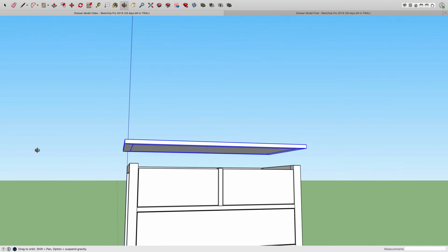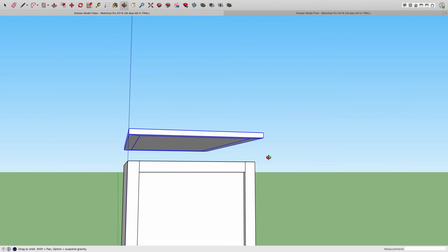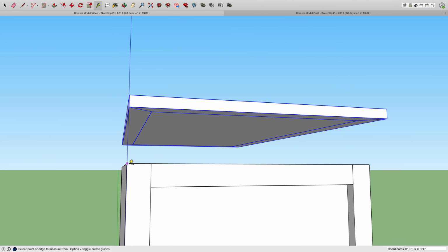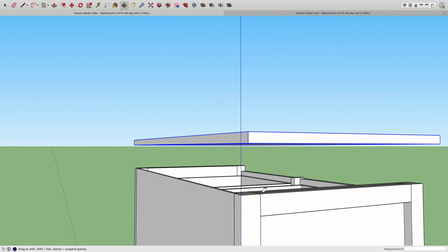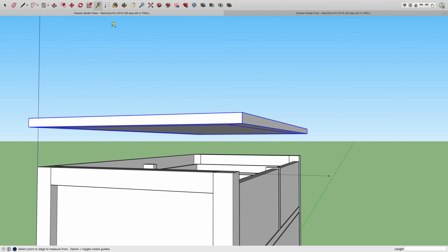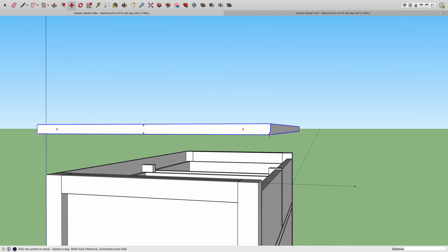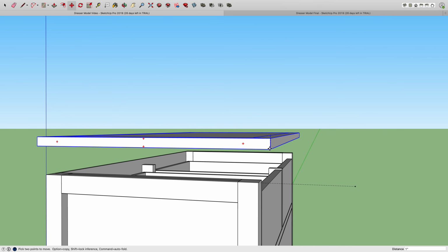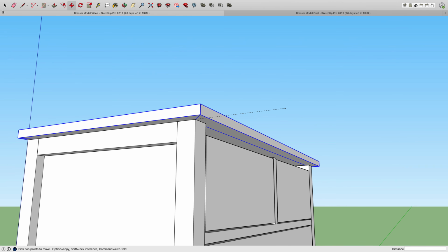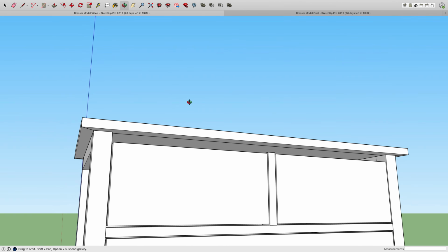Okay, I can't get this guy to move into place for the life of me, so I'm going to draw a little reference line. We'll create a line from right, making sure we get the right end point here, that point all the way through on red, so that should help us snap now. We get the move tool, get this guy, and come straight down on blue right to that point. There we go. Now we can just get rid of that little line, and that's in place.